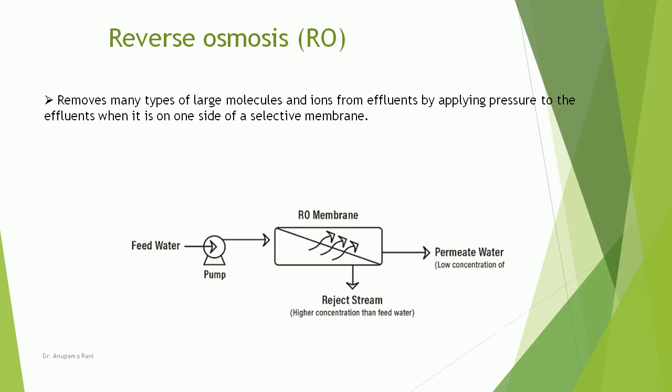The solvent of the solution is transferred through a dense membrane tailored to retain salts and low molecular weight solutes. When a concentrated saline solution is separated from pure water by such a membrane, the difference in chemical potential tends to promote the diffusion of water from the diluted compartment to the concentrated compartment in order to equalize concentration. At equilibrium, the difference in the levels between the two compartments corresponds to the osmotic pressure of the saline solution.